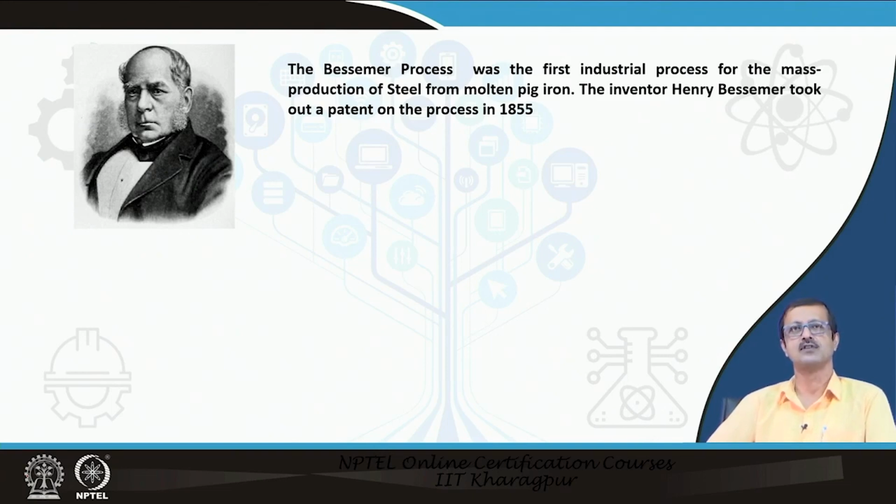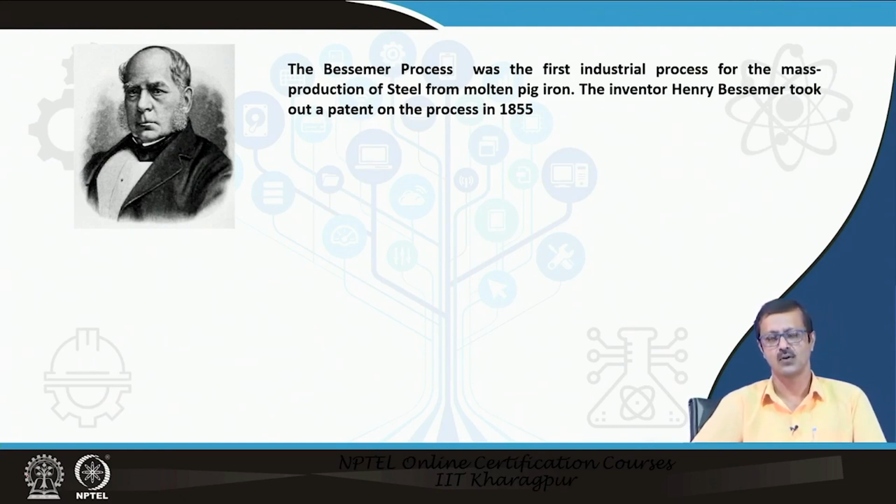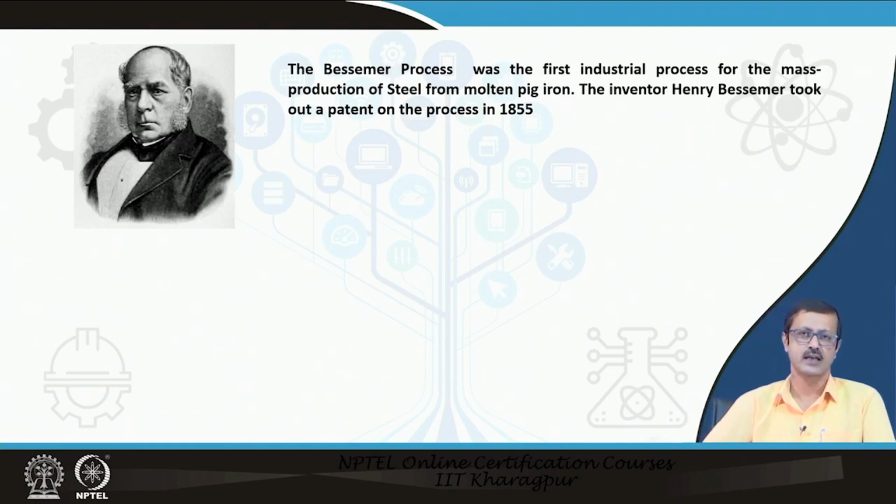So steel is available to us then, through the industrial revolution. And steel, as you understand, is one of the important materials for high-rise buildings, because with concrete or masonry it may not be possible to go that high. You need a material whose density is low and whose strength is very high. The strength-to-density ratio is very high in the case of steel, and that is a wonderful material for high-rise structures.